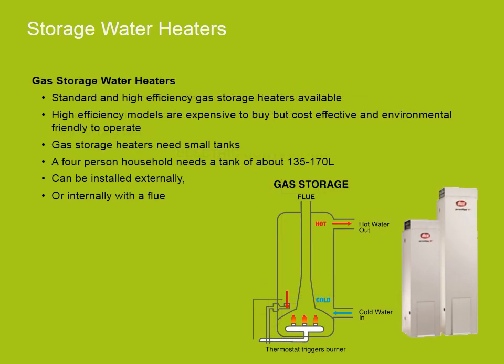Gas storage water heaters are available in standard or high-efficiency models. The high-efficiency models may be more expensive to buy, however they are more environmentally friendly and more cost-effective to operate. These gas heaters need only small tanks, as gas is available 24 hours a day and heat losses can be replaced quickly. For a 4-person household, one would only need a tank of approximately 135 to 170 litres. They can be installed externally or internally with a flue.